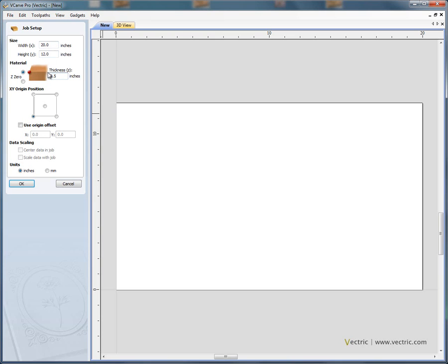Now it's very important to specify where you want the Z0 point to be. This is the point at which, on the CNC machine, you reference the tip or the bottom edge of the cutter, so that the Z0 point is known for the CNC machining. So here we'd specify it on the surface of the material, or we could specify Z0 to be on the table of the machine. For most projects, we teach people to use the surface of the material.